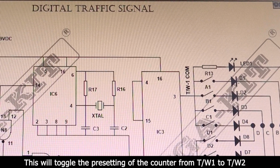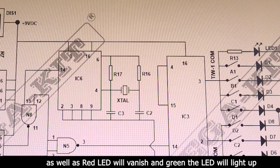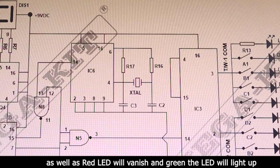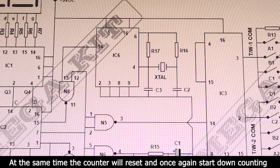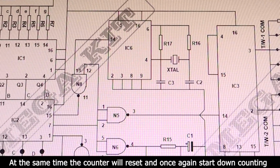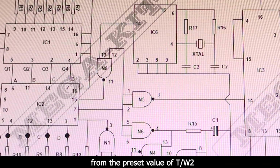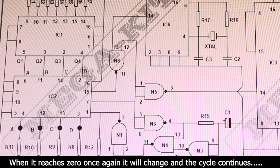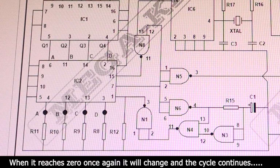This will toggle the presetting of the counter from thumb wheel 1 to thumb wheel 2, as well as the red LED will vanish and the green LED will light up. At the same time, the counter will reset and once again start down counting from the preset value of thumb wheel 2. When it reaches 0, once again it will change and the cycle continues.